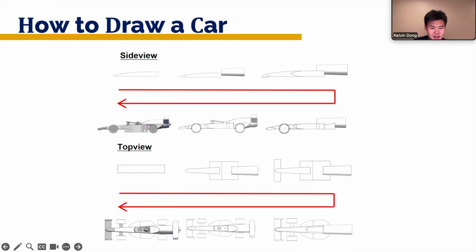You build surfaces off the skeleton. Second rule, assembly structure plus reference planes. From the beginning, think assemblies. The car is not one block. It's chassis, body, wheels, axles, tether line guide inserts, cartridge mount area, halo, and a lot of parts. Each of those should have reference planes that line up in assembly. Don't guess locations, you should define them.